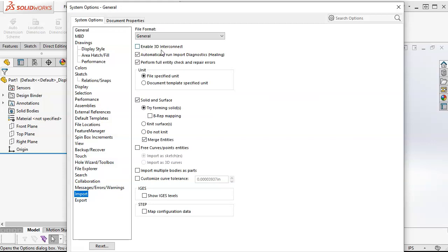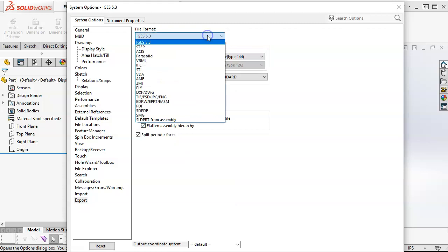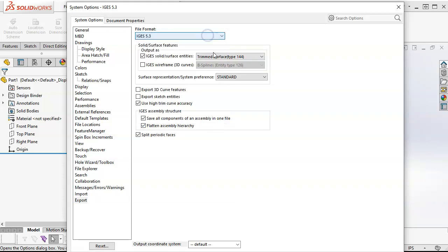If you have, say, an Inventor file and an X file, and you import it into your assembly, when you save it as a part, does it reference back to that original file, or does it keep it as an imported solid? So sometimes I'll leave that enabled, and other times I want it to just create a dedicated SolidWorks file, and then all of the export and settings for the various translations.